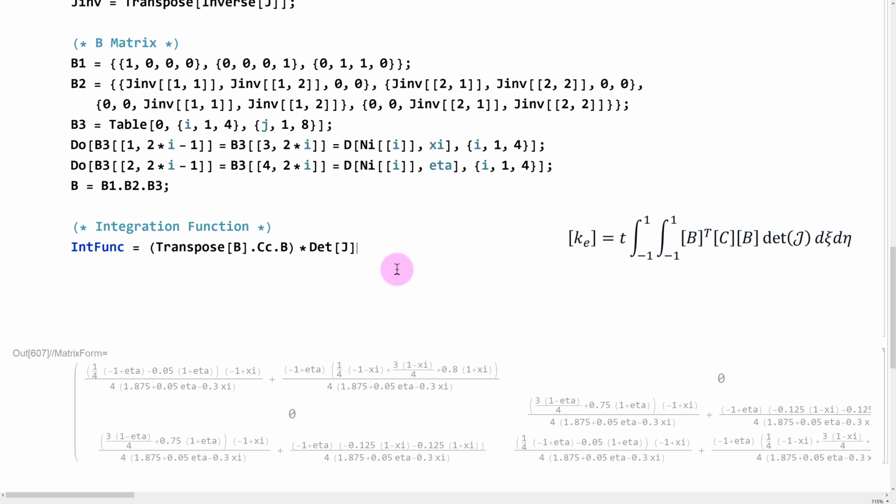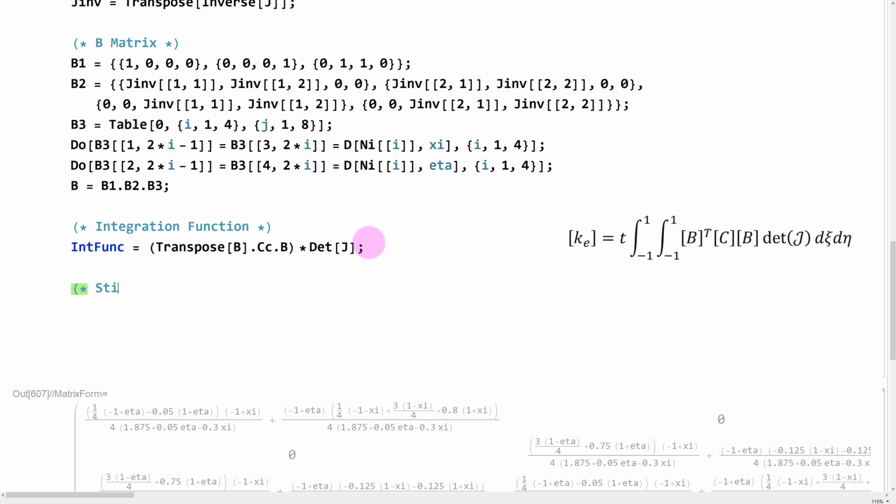So if we were to relate this to our traditional solid elements, this stays the exact same. The only difference is we multiply by this determinant of J to account for the size effect between the elements in our natural and our global system. So I'm going to suppress that. We're good to go. And then we can directly calculate what our stiffness matrix is.